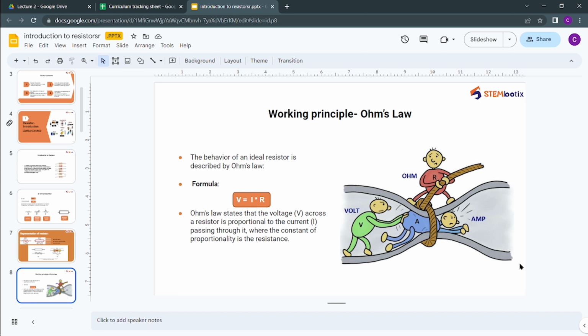First of all, power dissipation is something which we can call an undesirable quantity. At any instant, the power P in watts consumed by a resistor of resistance R is calculated as follows. We know that power P is equal to voltage into current. So voltage across the resistance into the current flowing through it is referred to as power in watts. So power P is equal to V into I, or V square by R, or I square R. This is the common formula for power.